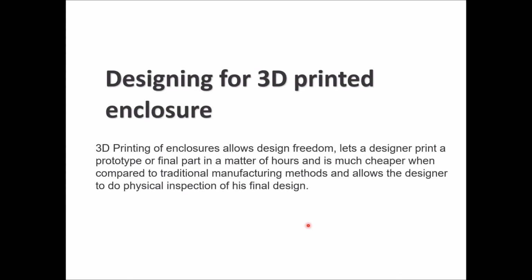We'll move next to designing for 3D printing enclosures. As I kept mentioning before, we will talk about enclosures in more detail because of their importance. A lot of modern world applications need enclosures, especially projects that enclose a PCB or a kind of mechanism, for parts that are usually handheld.